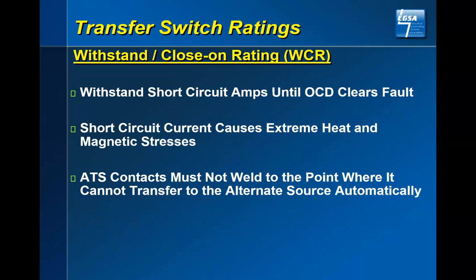It causes extreme heat. The way a transfer switch works is the more current you pass through it, the stronger it presses against its contacts. Whereas in a circuit breaker, it will open. In this case, I will sit there and I will continue to press against those contacts. I cannot weld those, and the transfer switch has to be able to still be operated.